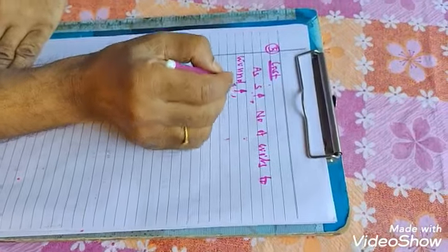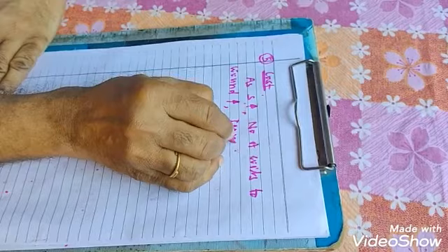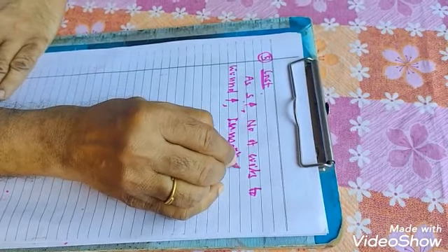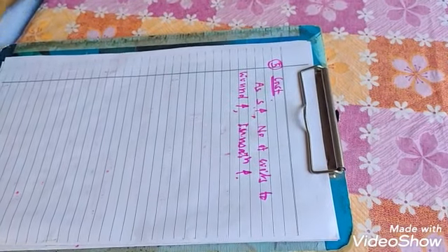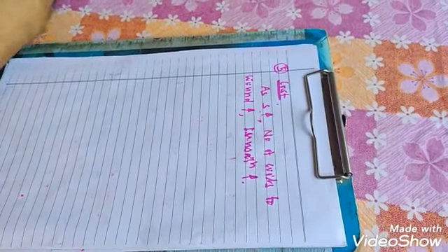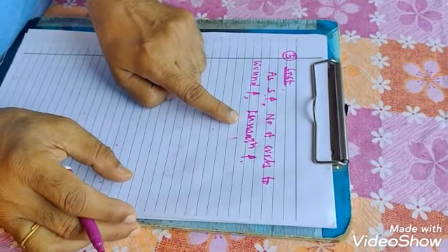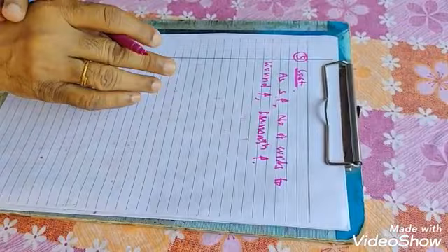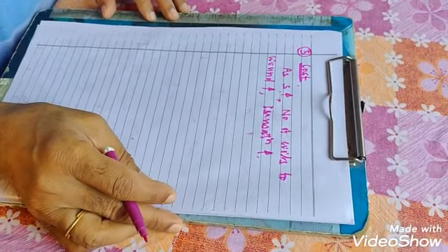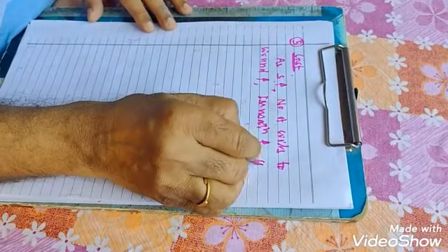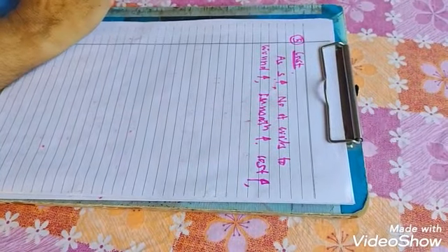Therefore, insulation increases. Each slot insulation increases. Okay, before putting winding in the slot, we have to insulate slots. As the number of slots increases, the quantity of insulation required is increasing. Therefore, the cost of insulation increases.